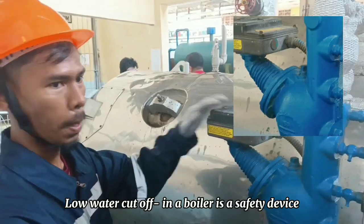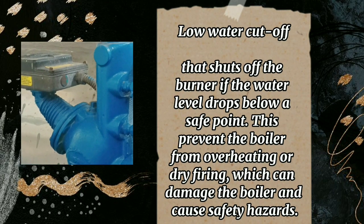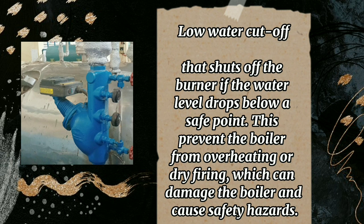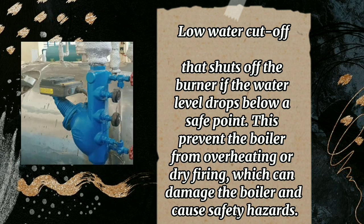A low water cutoff in a boiler is a safety device that shuts off the burner if the water level drops below a safe point. This prevents the boiler from overheating or dry firing, which can damage the boiler and cause a safety hazard. Feed check valve.